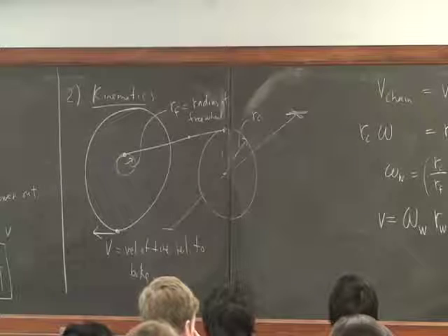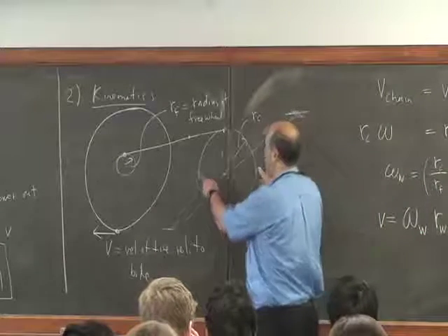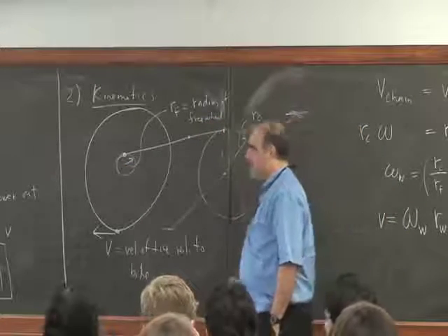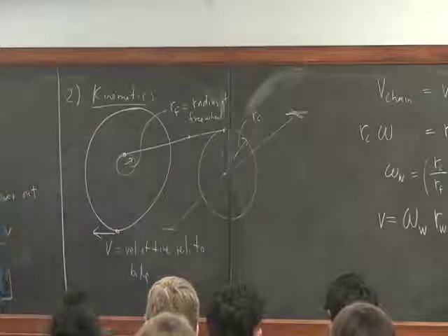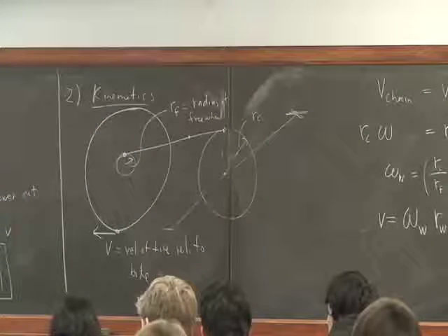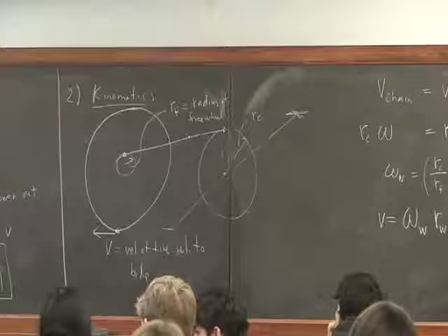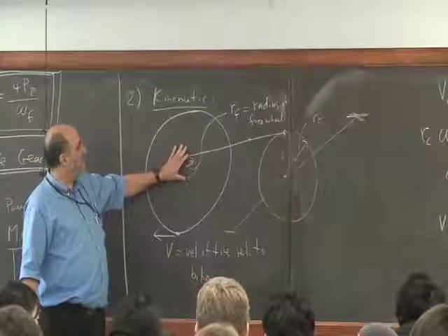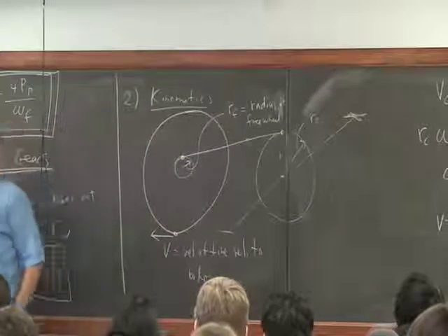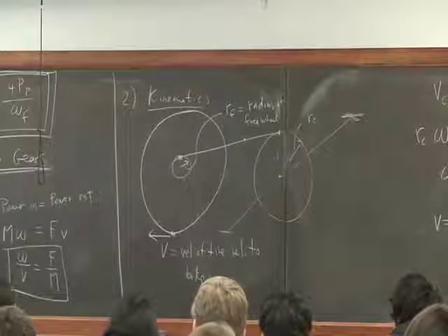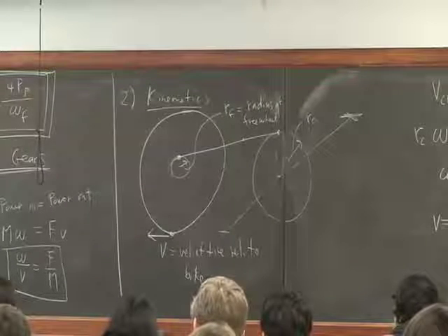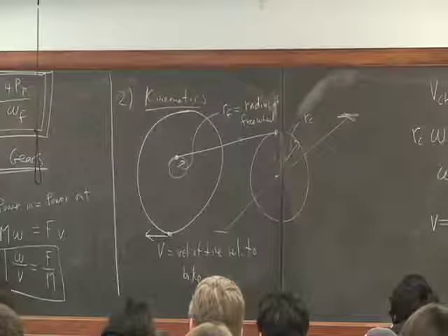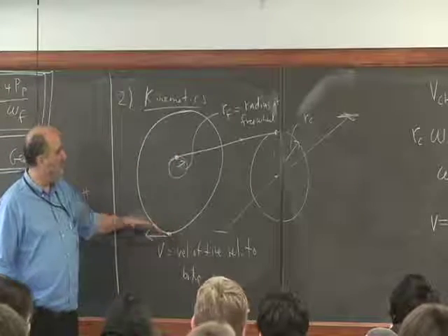So they have, for example, a 42-13 combination, which is a combination of 42 teeth up here and 13 back there. And these things come in standard sizes, say 52, 42, and what's the small one? 28? 30, 28. Whereas these back ones tend to be smaller, and they range from about 12 to 30, 32. I guess, what's the biggest anybody's seen there? 34. 34 in the back? Okay. For a very low gear, which means this thing has a low velocity in the back.